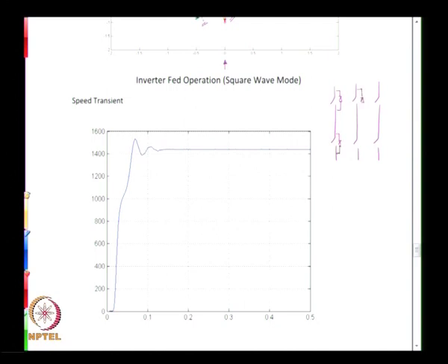So you have the diodes here, and this rail then forms the DC bus, and you connect a DC voltage here. These points then act as the output points of the inverter. This is a 3-phase inverter, and this is then given to the induction machine which is connected here.